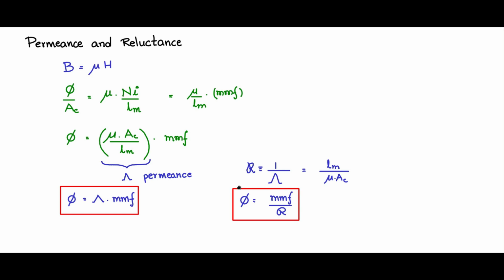This is also a popular way in which the flux phi and MMF are related. In fact, in many of the literature, sometimes people confuse this with Ohm's law in the electrical domain and call this current, this the potential, and this equivalent to the resistance. Reluctance is not equivalent to the resistor. Reluctance is not a dissipative quantity, and phi here is not a kinetic term. d phi by dt is the kinetic term, as we saw. To conserve both the units and power, it is d phi by dt which is the kinetic term in the magnetic domain, and MMF is the potential term.